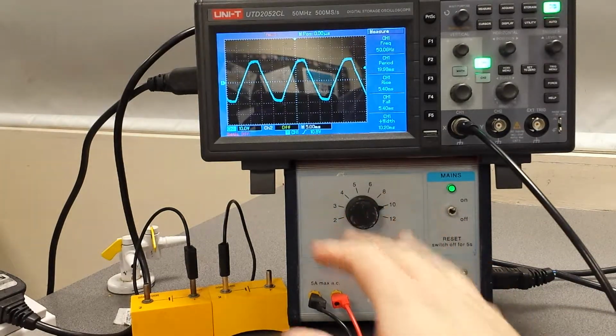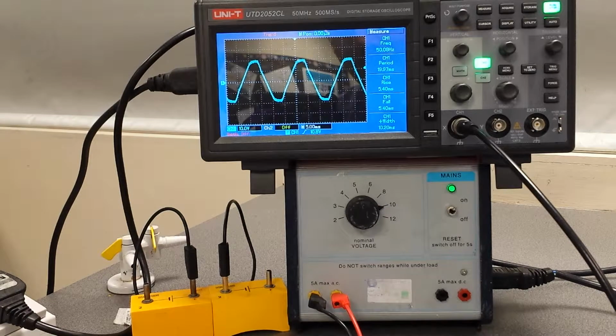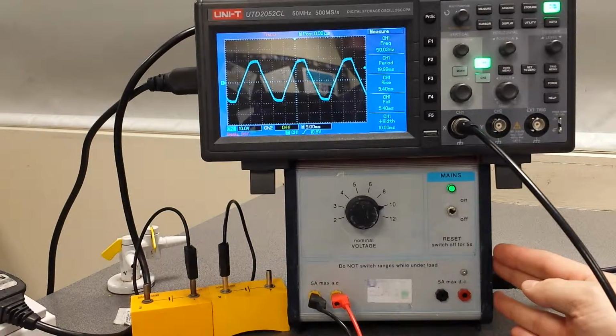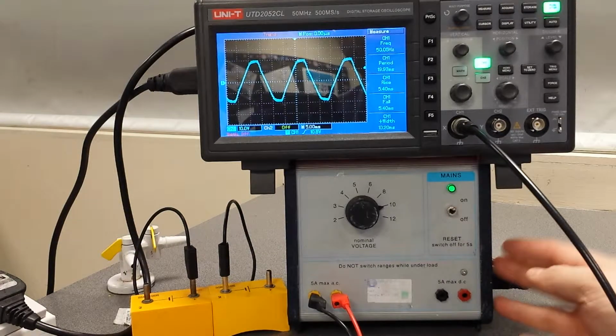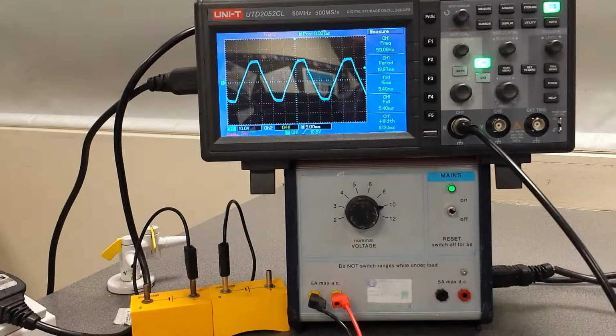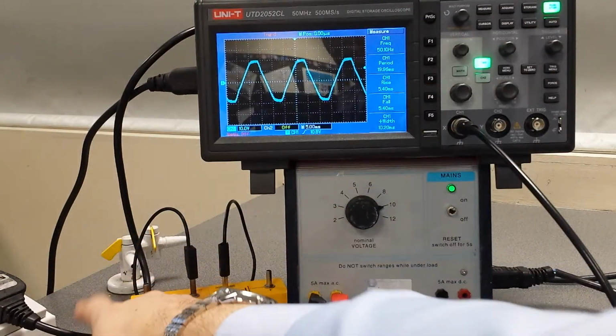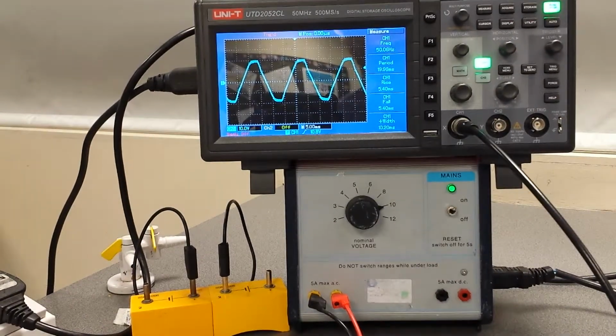Now, I can't change my frequency because the frequency of mains is 50 Hertz. That comes from the idea that the power supply, here we've got the lead going to the power supply and it's connected to the mains, it's just over here, a mains lead. The electricity is created from a source which is rotating at 50 cycles per second. So there's magnets in a coil of wire, or a coil of wire in a magnetic field, and that oscillates or spins around once every 50th of a second.